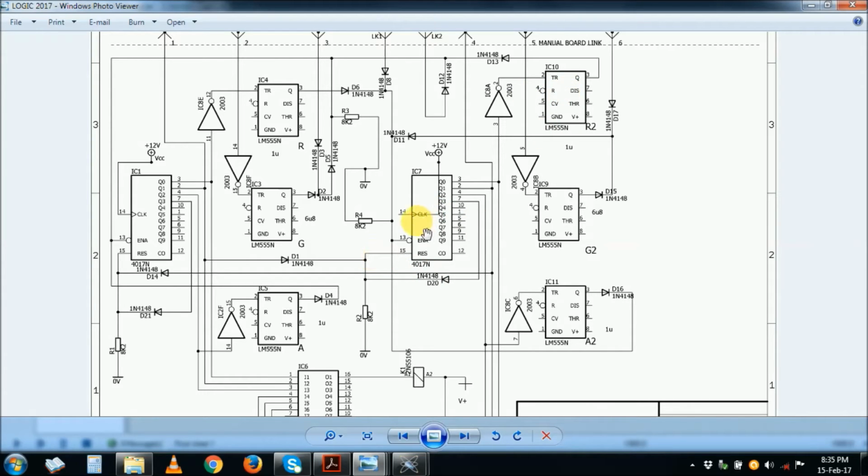So when this one is timing, this one will come here, and then will step to what? When it goes low, this one will step from number 3 to number 2, right? As you can see, if it goes to number 2 here, follow that path. We ignore this path first. It's going up there, but I want you to come back through here. Number 2 is coming here, it comes there, and it resets this IC. So whichever starts to count to number 2 will actually reset the other one.